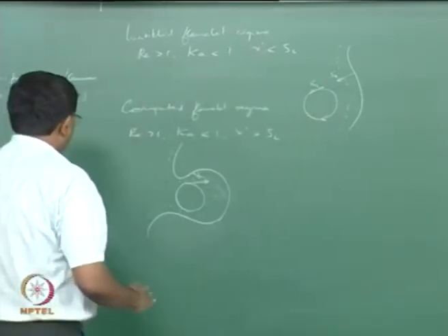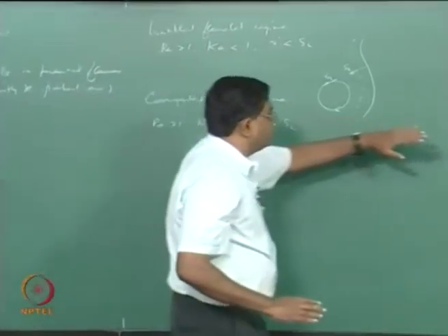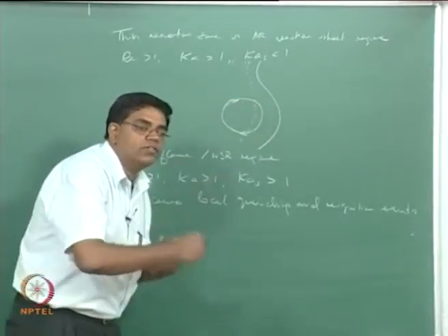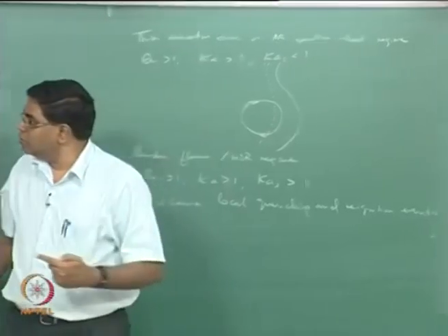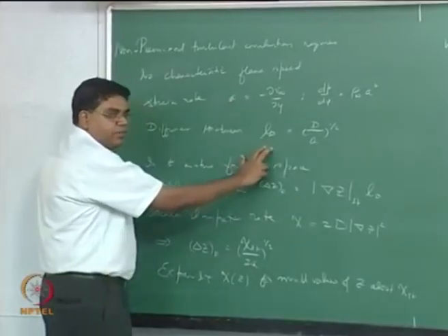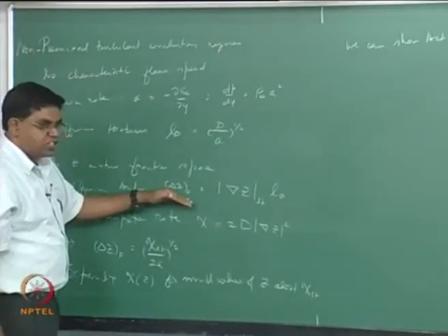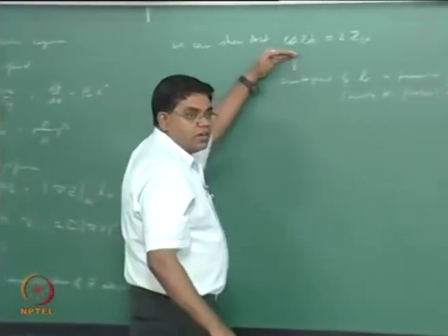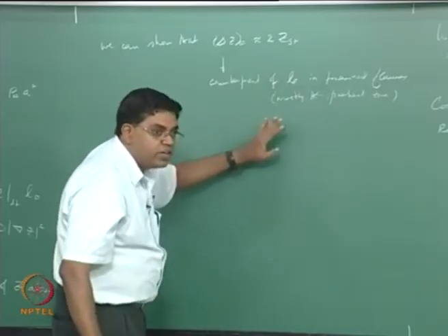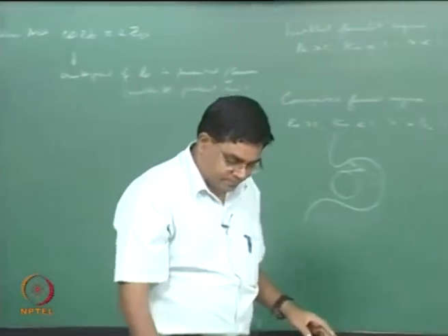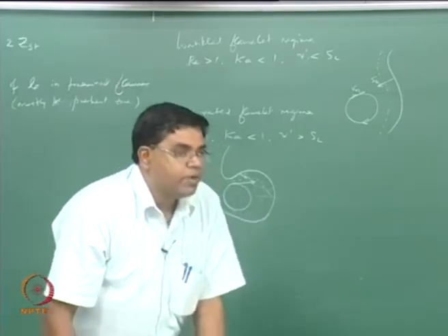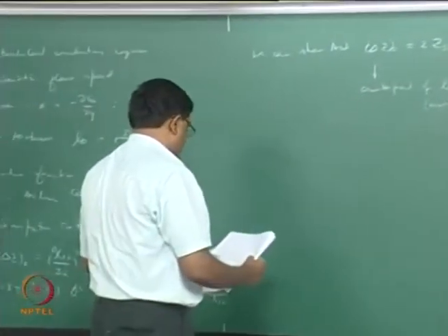So effectively in most of these, up to here, we have been mainly interested in the premixed flame regime diagram, what the preheat zone is doing relative to the eddies, right. So similarly, if you are now thinking about a corresponding diffusion thickness for the flame, we should be worried about this in the mixture fraction space, how that is going to actually interact with the eddies, and that is like the counterpart of mostly the preheat zone of the premixed flame. And here again the laminar ideas are coming back to help us.